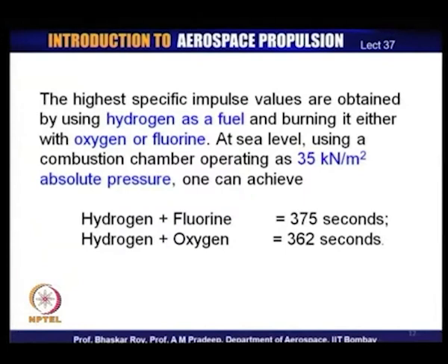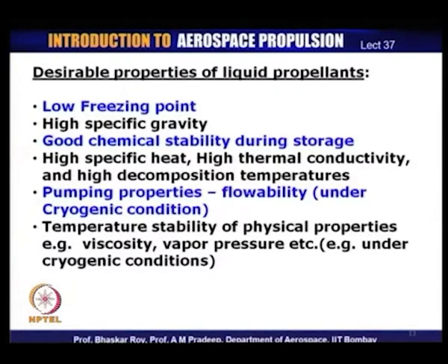So, more and more people are using hydrogen and oxygen because they are clean fuels and their product normally is in terms of steam, which is largely water. So, hydrogen and oxygen give very good specific impulse, not the best, but very good, and they are normally clean fuels. Now, if you take all this into account, we can talk in terms of certain desirable properties of the liquid propellants.